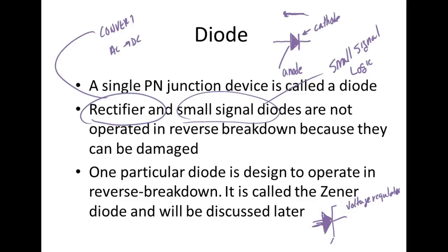But it's regulated. It's got a sense circuit in the regulator, and when you try to load your alternator, as soon as the voltage tries to drop because of the internal resistance of the alternator, it raises the energy to the rotor, which keeps the voltage up.